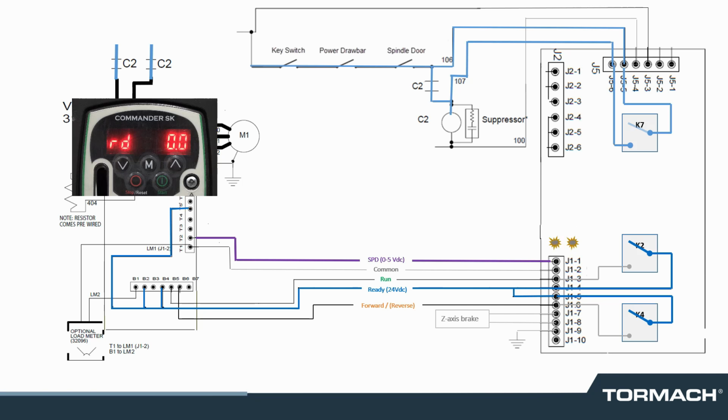The machine control board then sends 24 volts DC signal back to the VFD through the closed contacts of relay K2, connected to J13 and J14 as a run command. This signal initiates the spindle rotation, if no other signals were applied yet, in reverse.